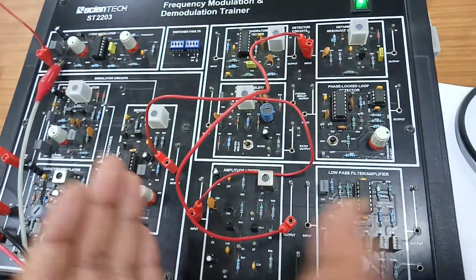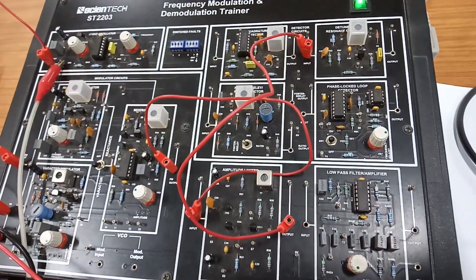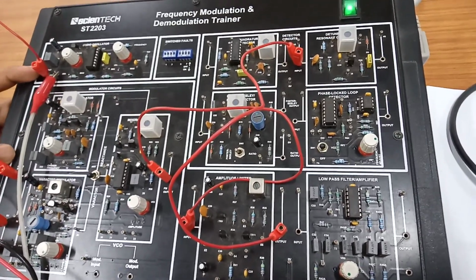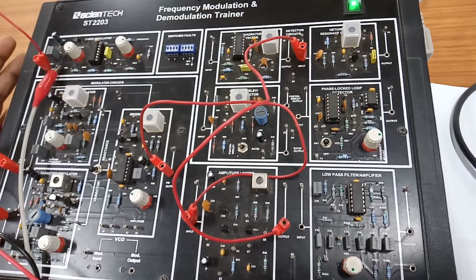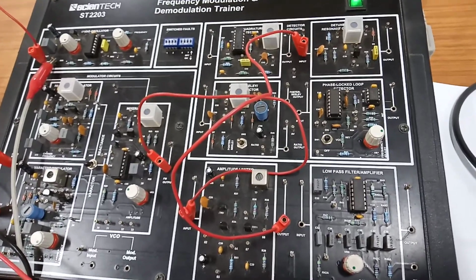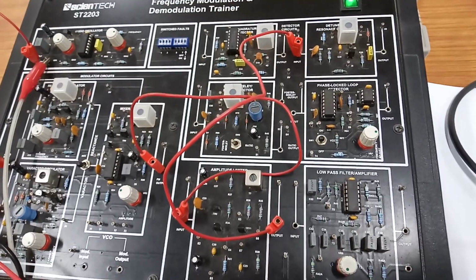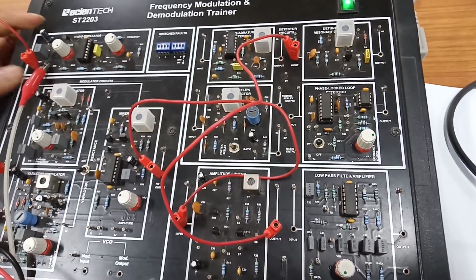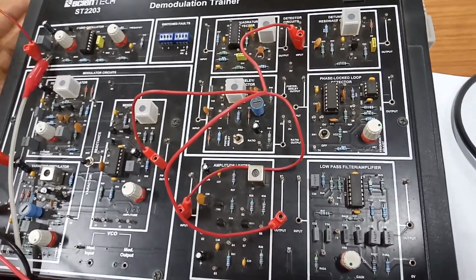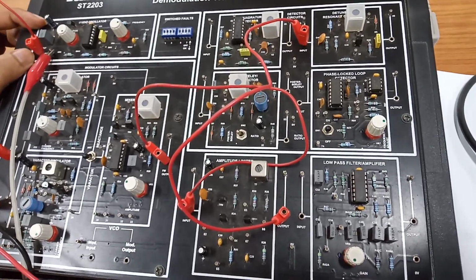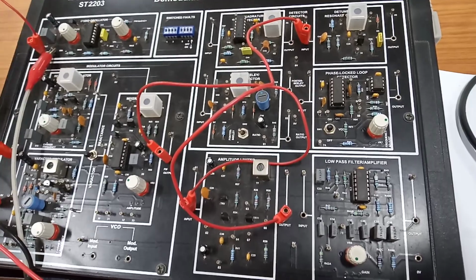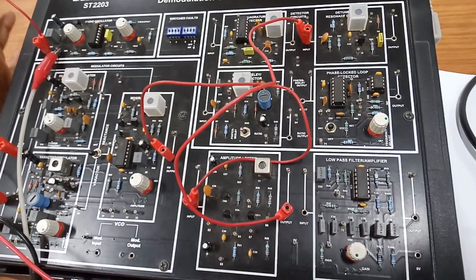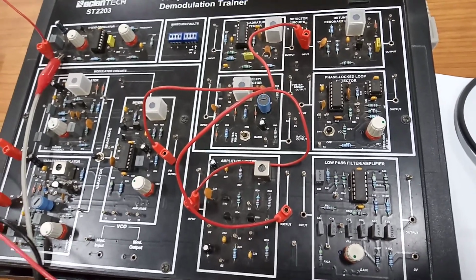This particular circuit we are performing is for demodulation. We are going to see whatever audio signal we were transmitting from the transmitter part, we are going to receive the same at the receiver part with 90-degree phase shift. As I told you, the quadrature system of demodulation gives a 90-degree phase shift. We will see what I am talking about. Whatever information, whatever audio signal, whatever music, whatever commercial, whatever traffic update, whatever be the information in this audio signal that we are considering here as a message signal is going to get retrieved at the receiver part. It means the information is getting conveyed, or the communication has taken place.